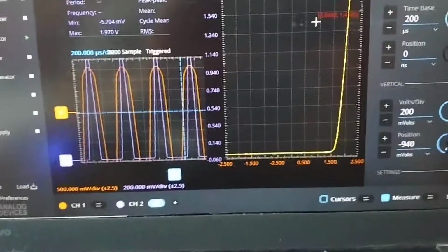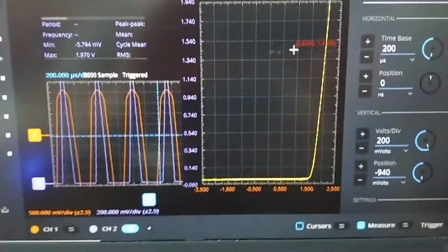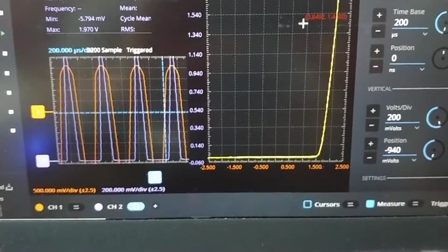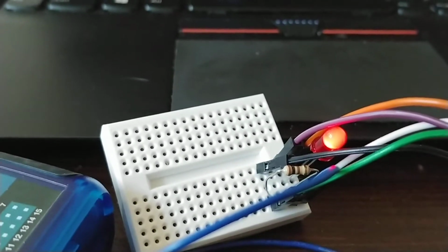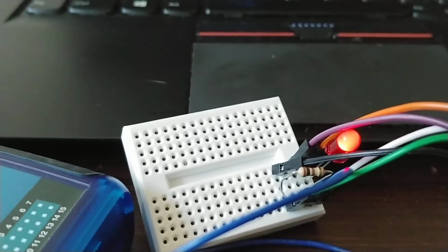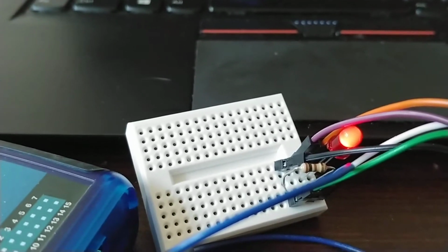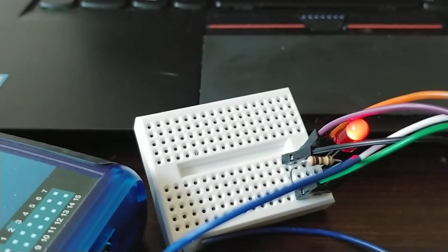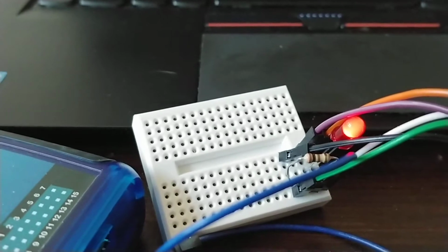So you can test transistors like this. It's a little more complicated, and it's dependent upon knowing the exact value of the resistance that we're measuring things across. And if you want to measure smaller currents, you use a larger resistor. There's test equipment, IV curve tracers and things like that, that automatically switch that resistance so that you can zoom in where you want.